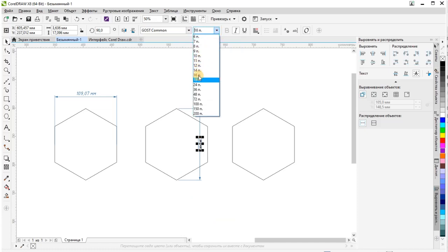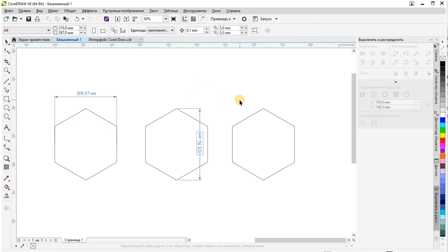You can customize the extension lines on which dimension lines rest. You can specify the distance between the extension lines and the objects that are measured and the length of the extension overhang. Extension overhang is the portion of the extension line that falls beyond the dimension arrows.